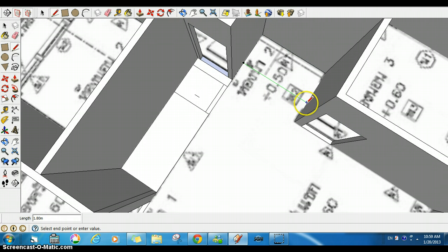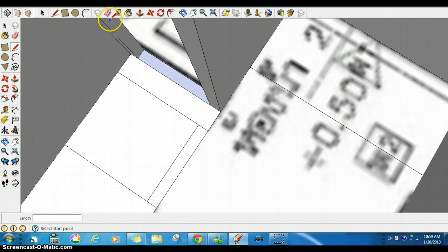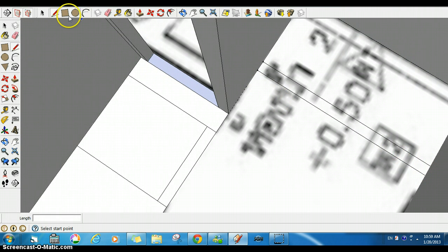Draw that line right there. Escape. Zoom in. Okay. 0.1, enter. Draw my other line there. Right. Oops. Escape. As you can see, this did not get highlighted. So somewhere I'm missing where I'm touching the wall, and that's why I didn't close this area.